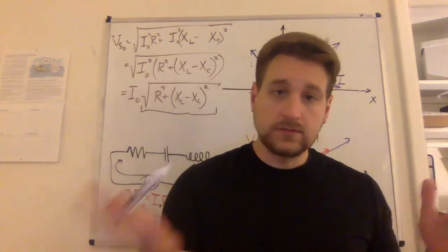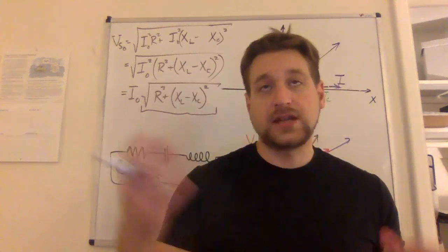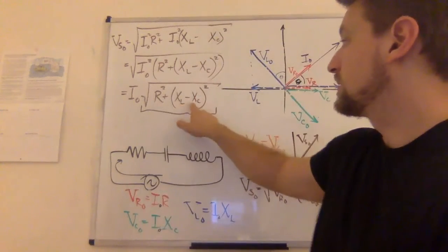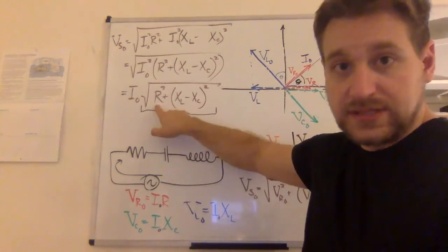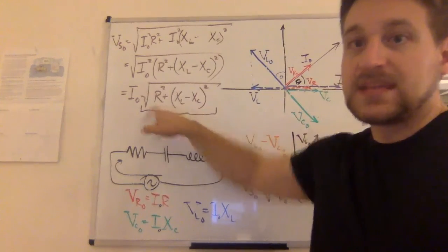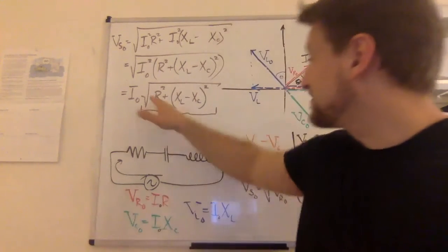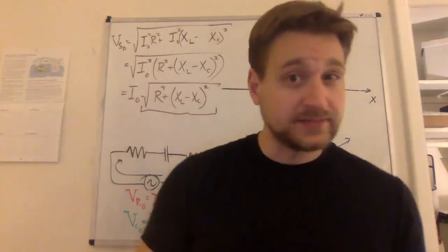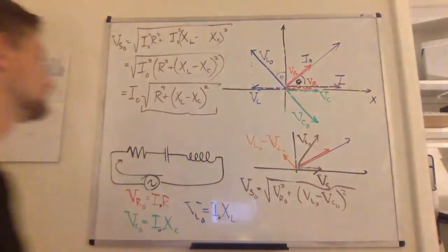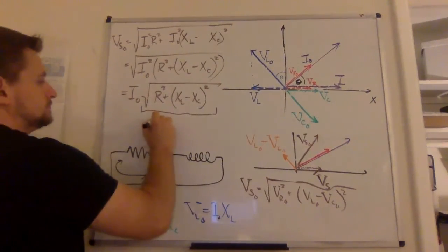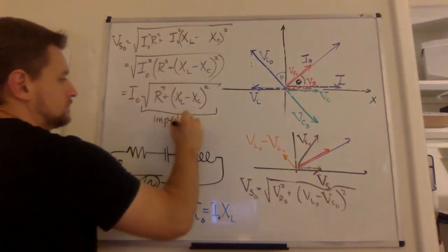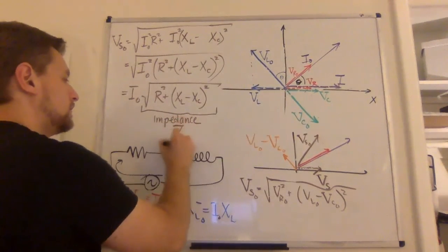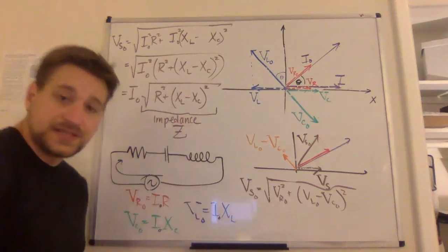It's not quite reactance because we've got reactive pieces and just plain old resistive pieces. It's not quite resistance because we also have reactive pieces, so we make up a new name. Same idea. Call it impedance, and we use the symbol capital Z.